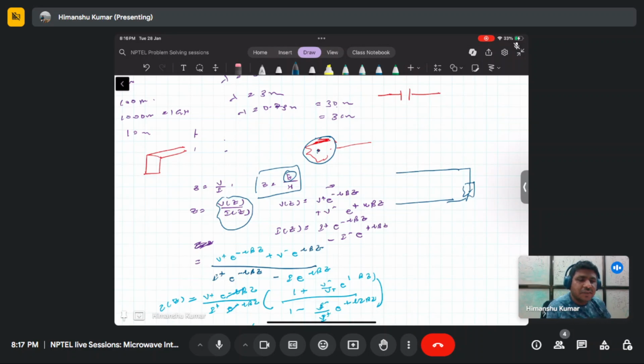If you solve the boundary conditions for a waveguide compared to the boundary conditions for, let's say, a coaxial cable line or planar guide lines, then the boundary conditions will suggest that there is no existence of TEM mode in the waveguide, compared to the existence of TEM mode in the coaxial line or other two wire kind of transmission line.